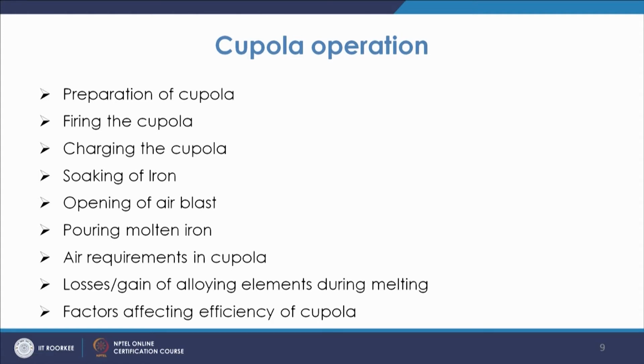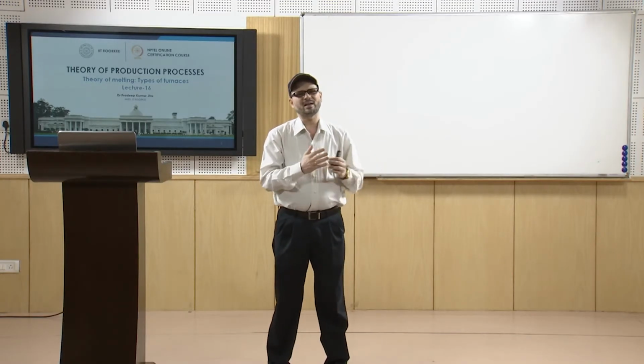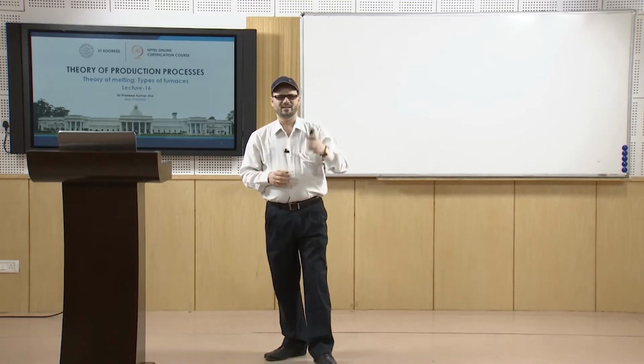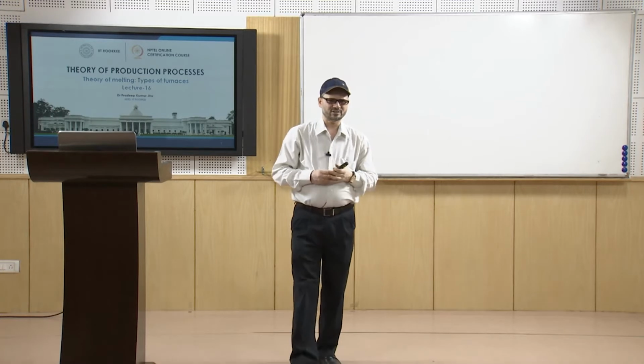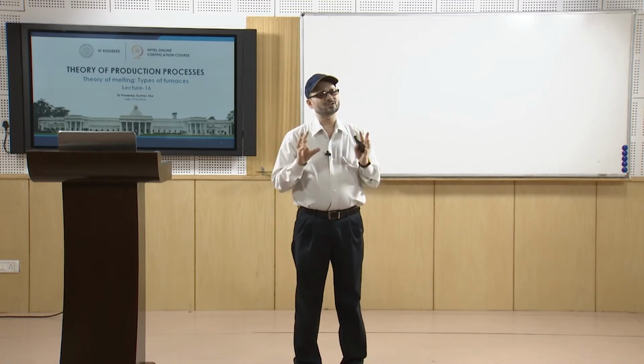There will also be loss and gain of the alloying elements in the cupola. That also needs to be understood. During cupola melting many a time the alloying elements, like manganese or silicon, or even carbon, may be picked up or lost. So, this is important.